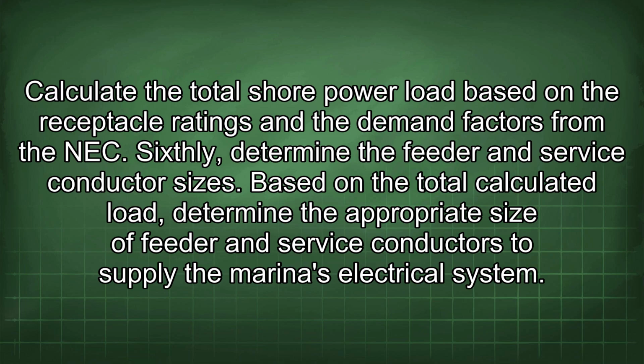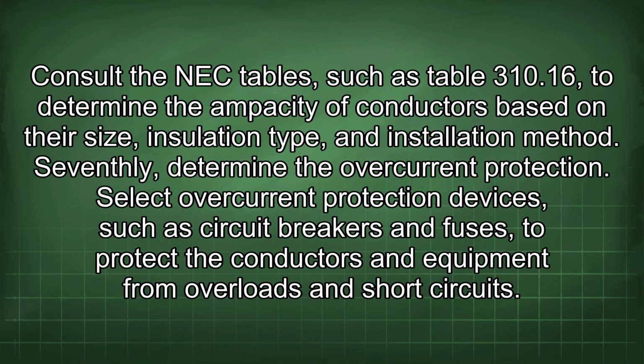Sixthly, determine the feeder and service conductor sizes. Based on the total calculated load, determine the appropriate size of feeder and service conductors to supply the marina's electrical system. Consult the NEC tables, such as Table 310.16, to determine the ampacity of conductors based on their size, insulation type, and installation method.